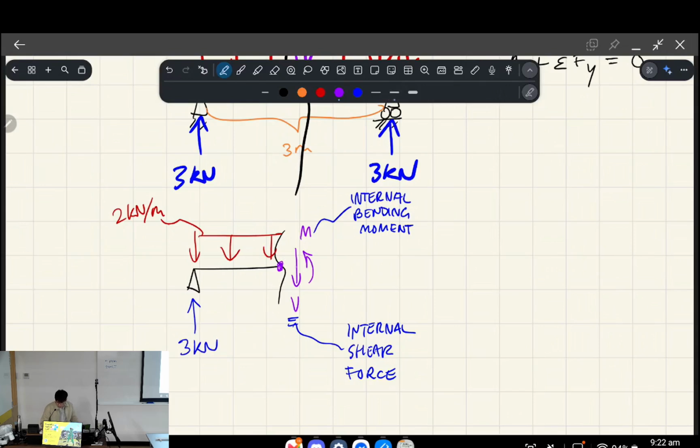And there's another one, which I'll show you as well. So N basically represents axial forces, so that's tension and compression. But for a beam, unless the beam is experiencing some kind of horizontal external loading as well, so let's say the beam is being pulled for whatever reason, if we've got a pulling force on this beam, of, let's do a different number, 7 kilonewtons, basically we've got 7 kilonewtons of tension that's induced in the beam as well, which we have to consider.